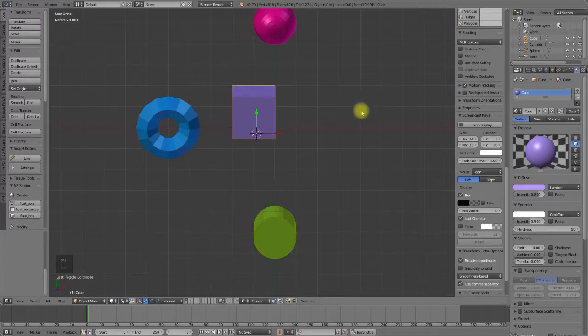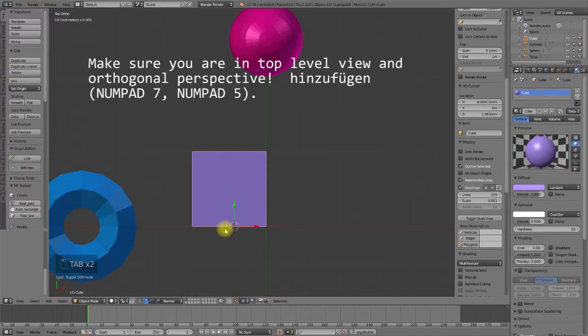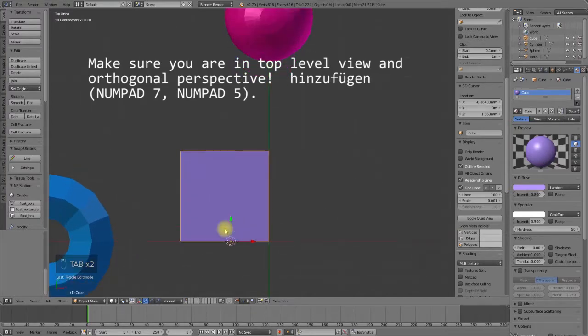Make sure we have the snapping function activated, use the snapping target closest and switch to increment, so it will use the grid now. And here we can decide if we want to have absolute grid alignment, so no values in between. Zoom in until you see the subgrid.